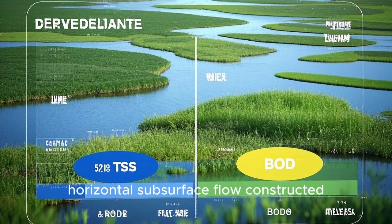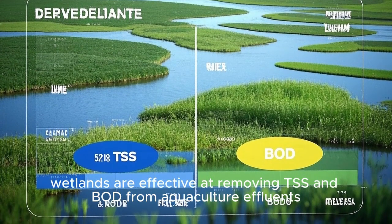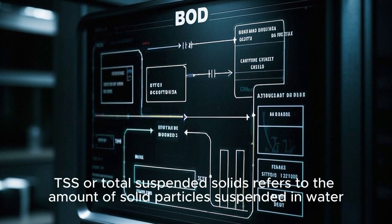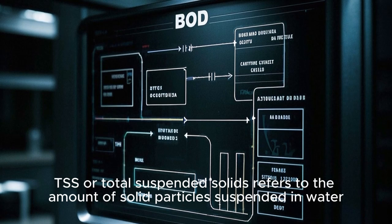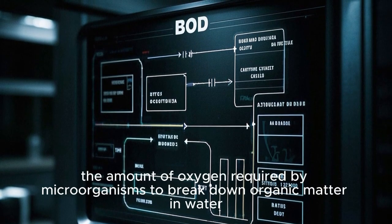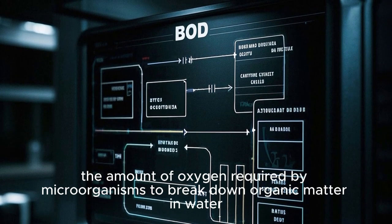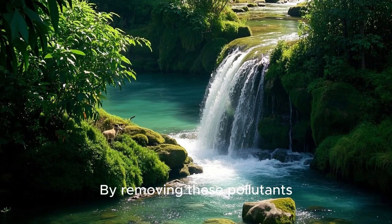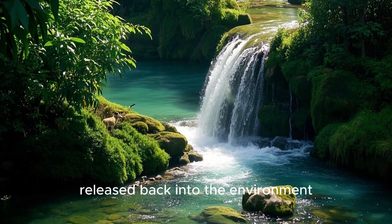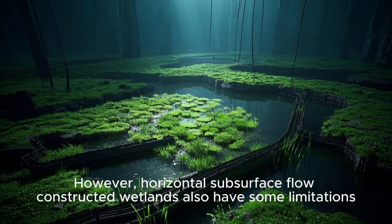Second, horizontal subsurface flow constructed wetlands are effective at removing TSS and BOD from aquaculture effluents. TSS, or total suspended solids, refers to the amount of solid particles suspended in water, while BOD, or biochemical oxygen demand, measures the amount of oxygen required by microorganisms to break down organic matter in water. By removing these pollutants, the constructed wetland can help to improve the quality of the water released back into the environment. However, horizontal subsurface flow constructed wetlands also have some limitations.